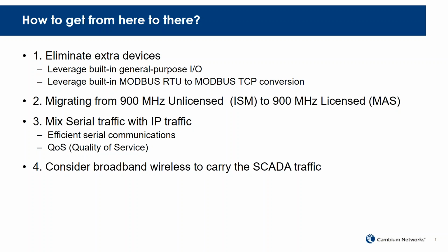We've also recently added this Modbus RTU to Modbus TCP conversion. So if you have an older PLC or RTU that only does serial communications, with the latest version of cnReach, there's a software converter built right into the unit. So oftentimes when customers do these migrations, without this feature, you would have to have an external box that does that conversion. There's a number of companies out there that sell these little boxes that would sit between the radio and the PLC. But by bringing this inside the radio, the software eliminates that extra point of failure and the cost of that external device.